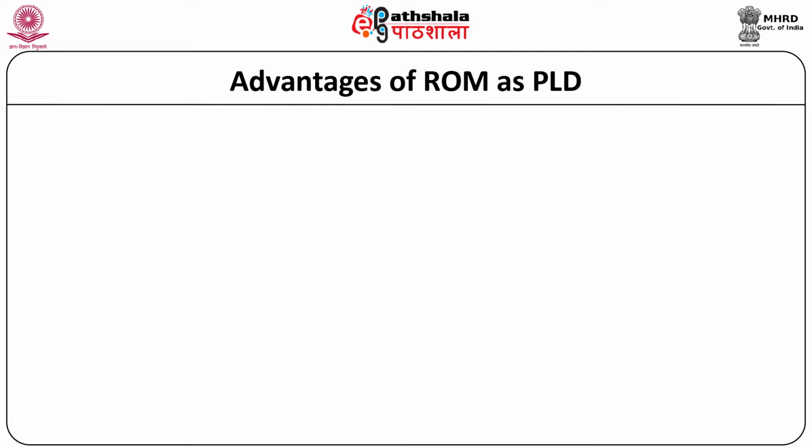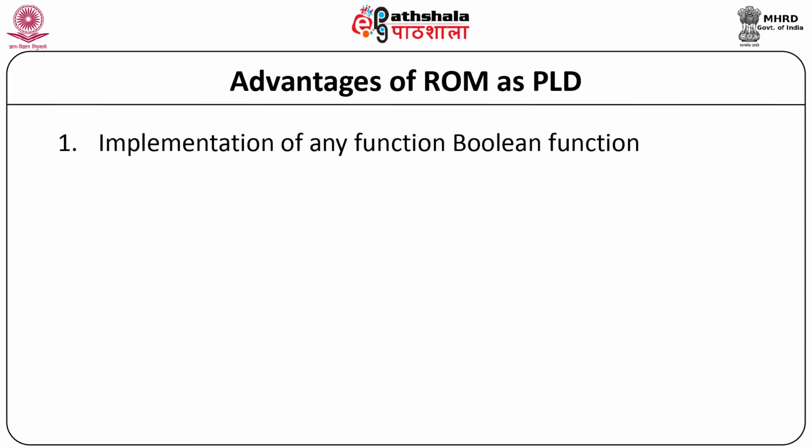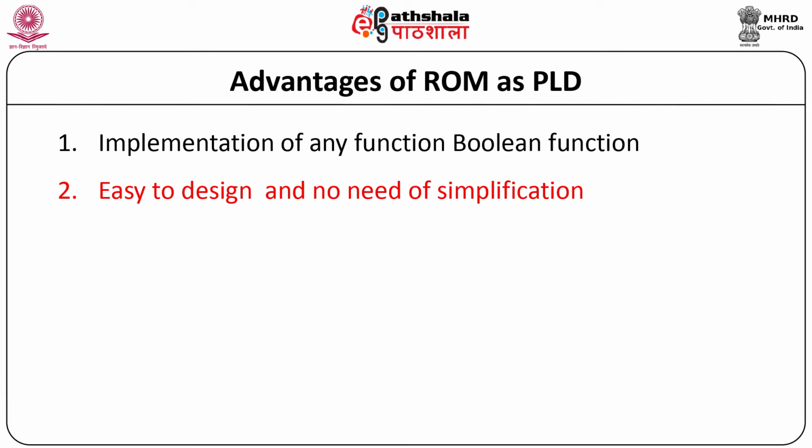Let us now talk about advantages of ROM as PLD. ROM can implement any function because all the minterms are available. Second, ROM based design is easy to implement as there is no need of simplification or minimization of logic functions.